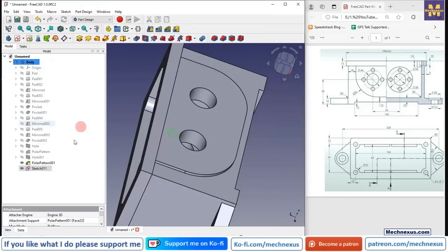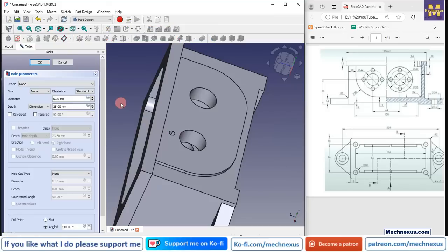Click on close, select the sketch, click on hole wizard, give the same values which we did, regular profile, and the size of my tapping is M10, depth is 18, but my tapping distance is of 16 mm, so I will select dimension and provide here 16 mm.